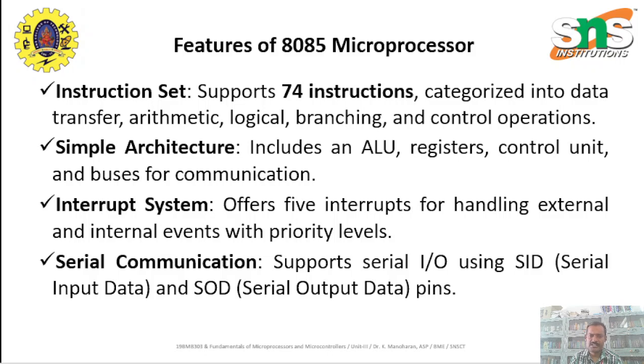And serial communication: it supports serial I/O using 2 pins. One is SID and the other is SOD. SID, serial input data, is for input data. SOD, serial output data, is for sending data. This is useful for communicating from a microprocessor to some other microprocessor, a microcontroller, a PC, or any other things.